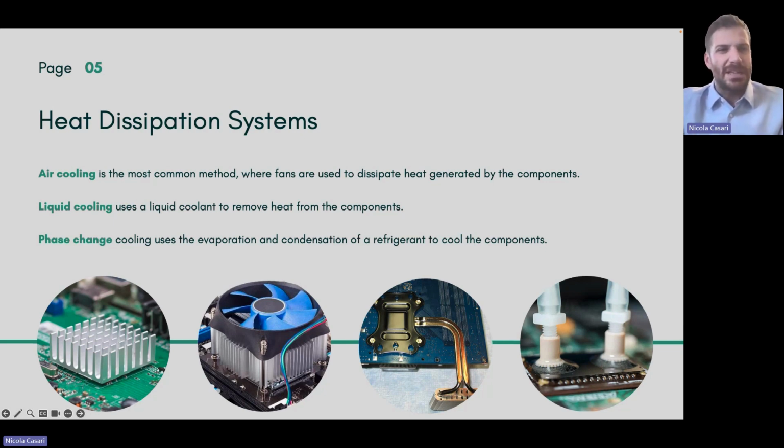Typically, we divide them into active and passive heatsinks. Active heatsinks are when fans are used to blow air through our component, and passive heatsinks are when the only driving force for the heat management is just the temperature difference between the device and the outer environment. Liquid cooling is where we have a liquid to remove heat. So when there is a coolant going inside our components, or being very, very close to the component to mitigate the temperature.